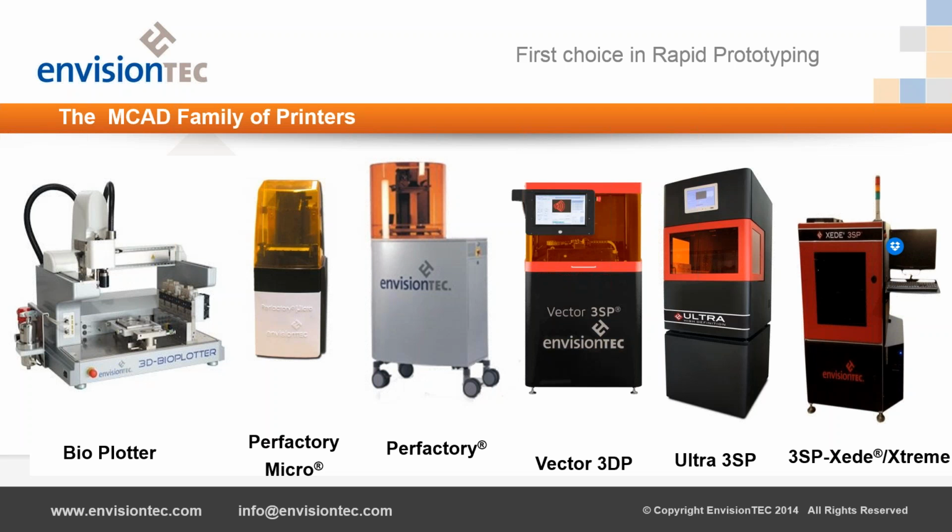That's the process where you take some solid material, heat it up, squirt it out through a nozzle, and build a part layer by layer. This process here is very similar to SLA, which stands for stereolithography apparatus, where it uses liquefied materials and cures them either with light or laser.